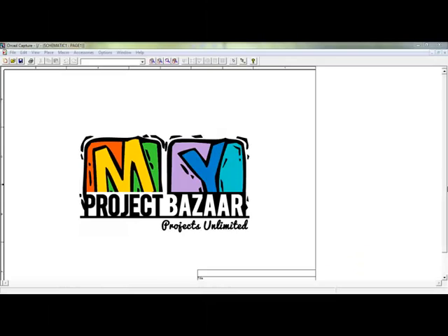Now I am going to describe the running procedure of our project. Here, the circuit displays the total overall MTCMOS basic switching bank circuit. Each and every base connection will be connected with separately given time allocations to perform the delay performance. Here I separated each and every bank circuit at 10 nanosecond differences. For each 10 nanosecond difference, these bank circuits will interchange their switching devices, and finally this will be provided as an output waveform structure.